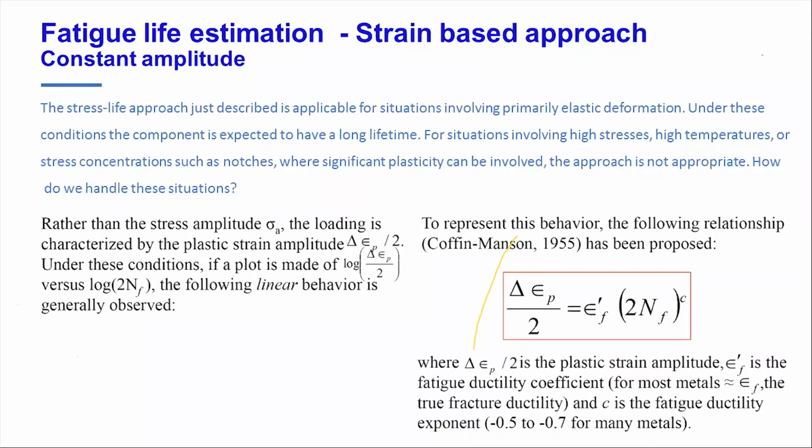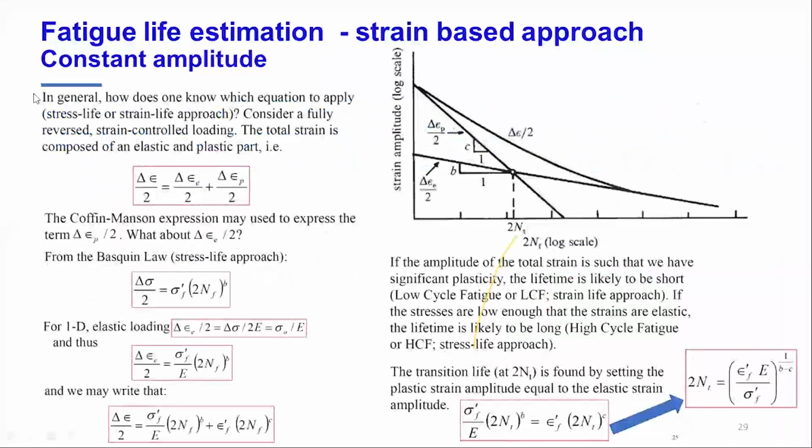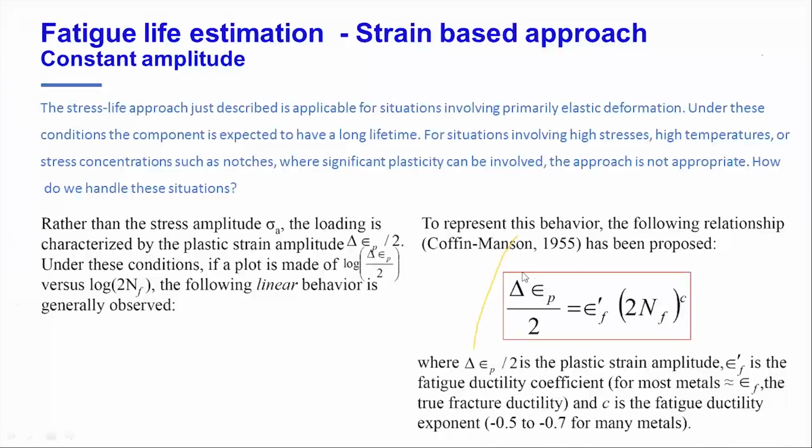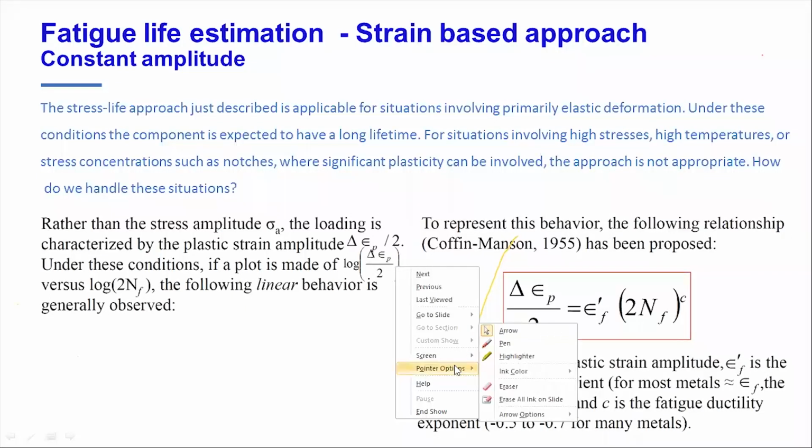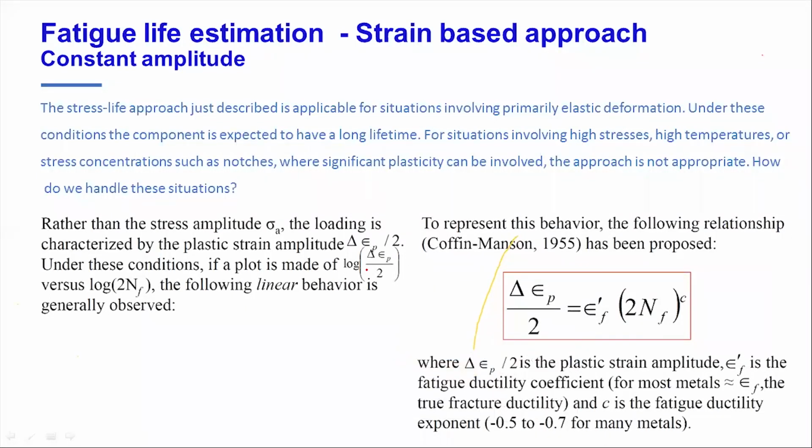So typically these strain-based approaches deal with high stress, or rather I should say high strain zones. Here, instead of taking your stress for fatigue calculation, what you focus on is your plastic strain range, which is delta epsilon p.